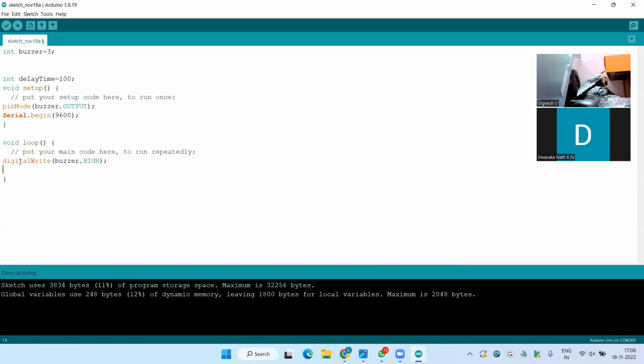Again here we need to give a delay. The delay time we already have. Again copy this one, paste it here. Here high is there, here I'm going to change to low. And the delay time is common.